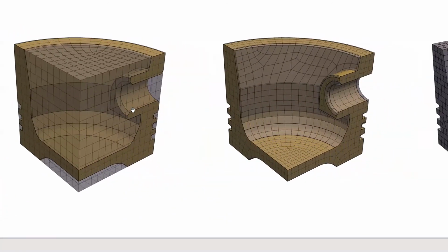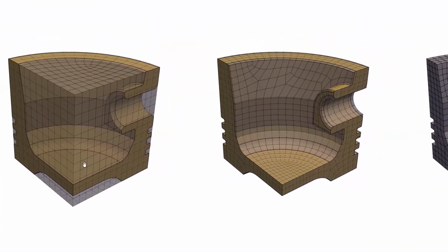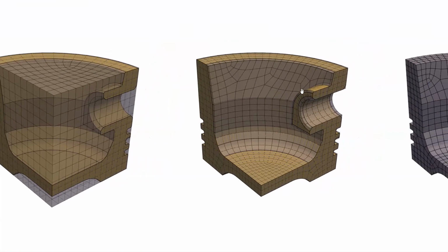And then further, maybe I still want a lot of accuracy on all of these surfaces, but I don't want to have to mesh all of these little fine features. What you can see here is that most of these surfaces are exactly body fitted, but where there are chamfers or fillets, we're just using a little extension off and getting really close to what the geometry is.